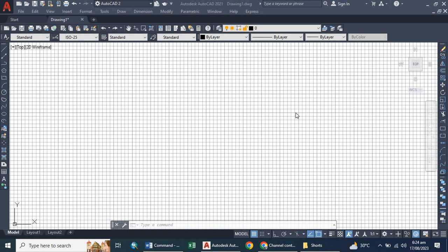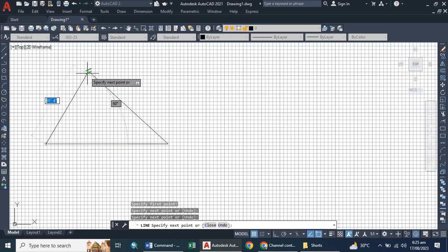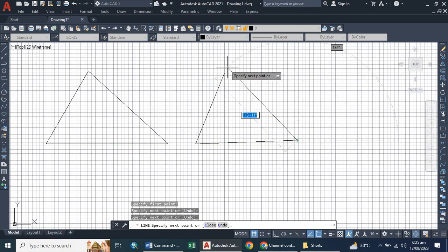In case you have a version of AutoCAD below 2016, for example 2013 or 2010, and you want to draw a hatch or gradient, first of all you should have a closed object. Nowadays, if you have a closed object you can execute the hatch and gradient command, but in the previous versions of AutoCAD you have to specify the boundary as well. If you don't specify the boundary, you cannot execute the hatch and gradient command in a closed object.